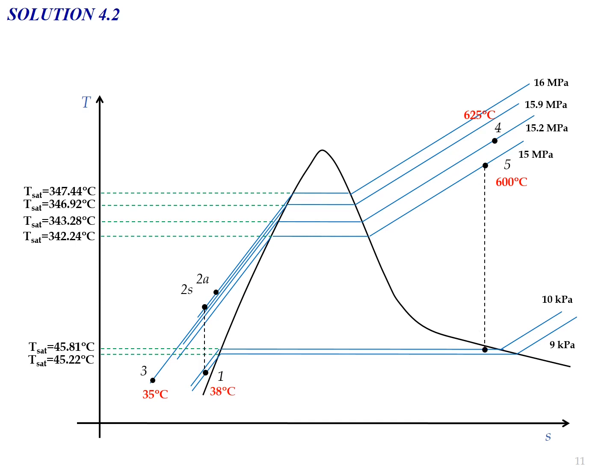And for state number 6, we can determine state 6s easily, where the intersection will be at the 10 kilopascal constant pressure line. From state number 5, we just draw the vertical line, so we get state 6s. State 6a and state 6s are located on the same constant pressure line of 10 kilopascal. Because we know that during our calculation state 6s is in the saturated mixture region, we just put the point for 6a slightly to the right of the point for 6s.